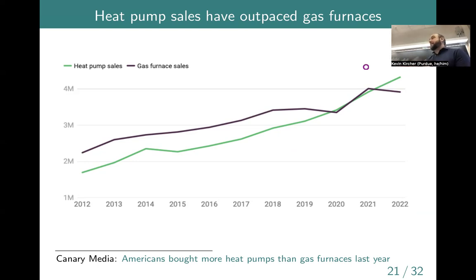So in some places, gas is expensive and electricity is cheap. In other places, it's the opposite. It also really depends on how efficient the machine is that we're using. If we're comparing an old gas furnace to a new heat pump, or a high efficiency heat pump built for good performance in cold weather, then that might tip the scales. But generally speaking, it's kind of a wash. There aren't huge energy savings potential on the heating side versus natural gas today.